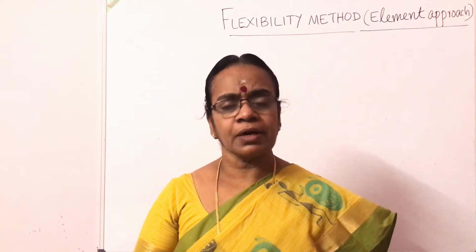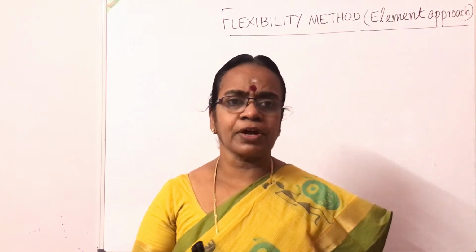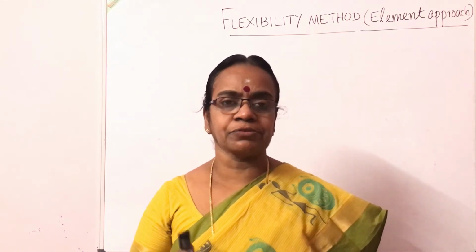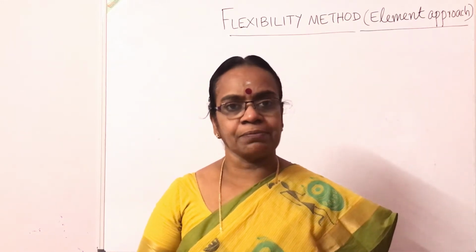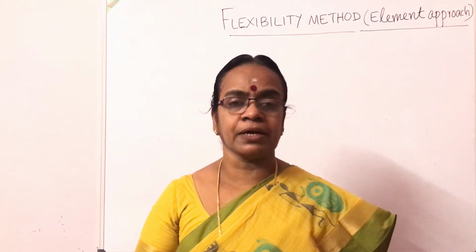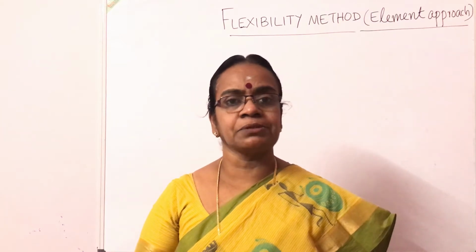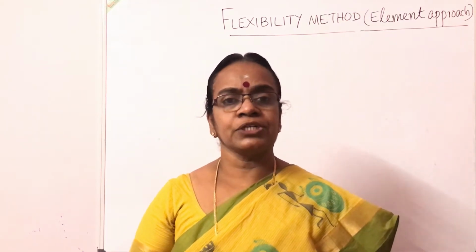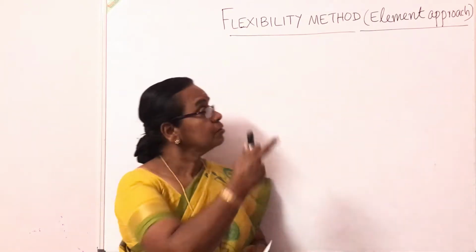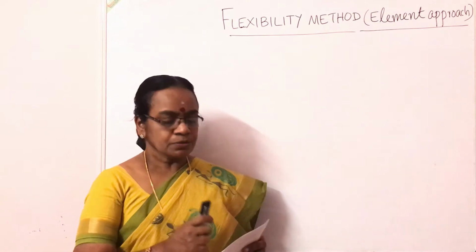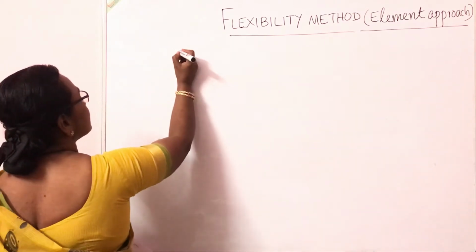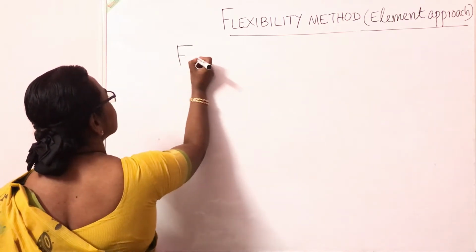Now what I'm going to do today is analysis of structures by element approach. When the size of the structure is very large, we have to split it up into several number of elements. Then viewing the structure as a whole and developing the flexibility matrix by unit load method or any other methods which you have studied in computation of deformations is not that easy. So the necessity for this element approach. By the element approach, we formulate the flexibility matrix using an equation.